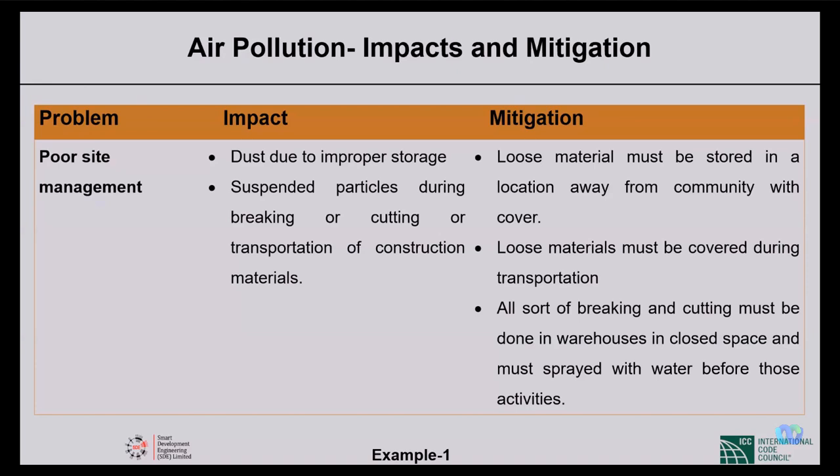So I will give you some examples. Here are the air pollution impacts and mitigation. Air pollution comes from poor site management. If you don't do proper site management, keeping your sand covered, keeping up the watering and that sort of thing, then there will be air pollution.